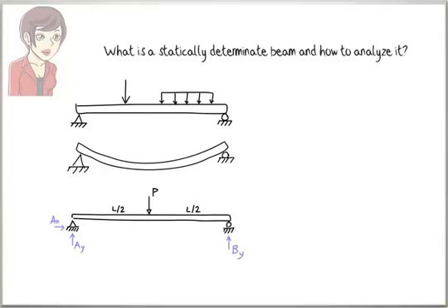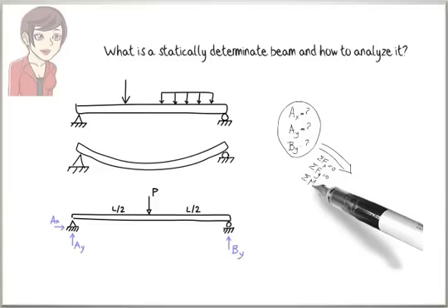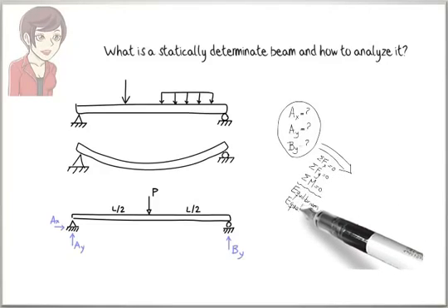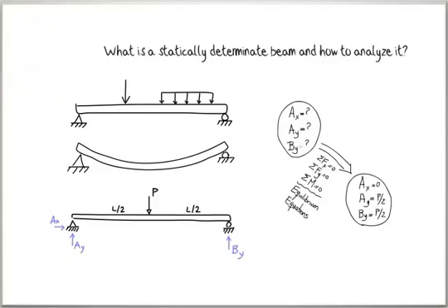Then, what is a statically determinate beam? A beam is called statically determinate if its unknown reactions can be calculated solely using the equilibrium equations. Now, how do we analyze such a beam? Before we can answer the question, let's review reaction forces associated with each type of support.